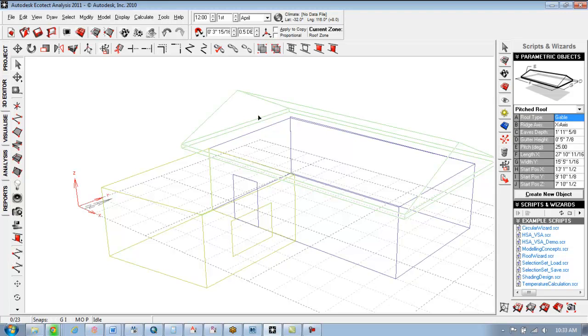If this is just an attic, then you're okay, or you might just model a small void here. If it's an example of like a church or something where that room opens up all the way to the roof, then you would have to cut out a void that was the size of the entire top plane. You wouldn't just model partitions around, put a floor and then put a roof on top of it. You have to think of it in zones. One of the descriptions in the help section actually tells you to think of it as if you were filling your building up with water. You would want it to be completely sealed in order to do these calculations.